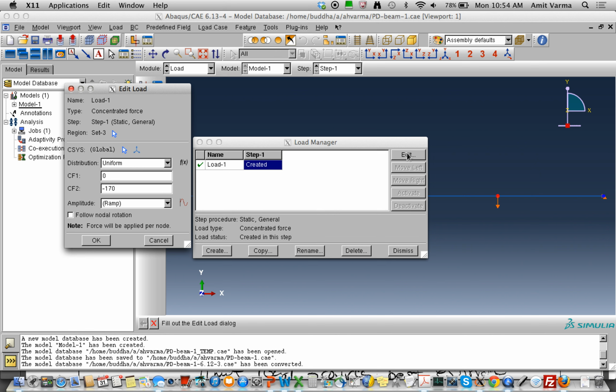So if I apply the loading in load control and give it 170 kips, what is the program trying to do? The finite element approach is trying to find equilibrium for 170 kips. It's not possible. So it will exit with an error and come back and tell me, I can't do this. That's all right. It went up to the plastic limit load and then told me that. So I can still post-process the results and I have the answer that I'm looking for.